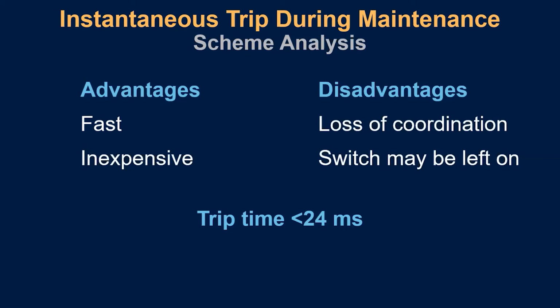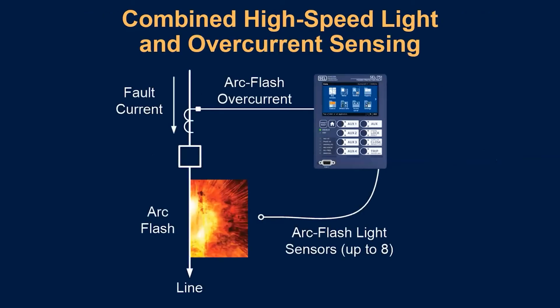So how do we take what's good enough, have some compromises, and make it better? How do we make an arc flash detection scheme that is secure, reliable, fast, and easy to use? So I'm going to introduce you guys to our light and current-based arc flash detection method, in which we will certainly still measure current from the system to determine that a fault exists, but we can determine selectivity by placement of a sensor, and we can determine that it is an arc fault specifically by what we're measuring with the sensor.